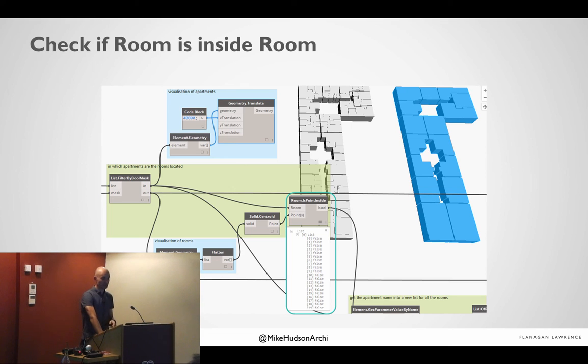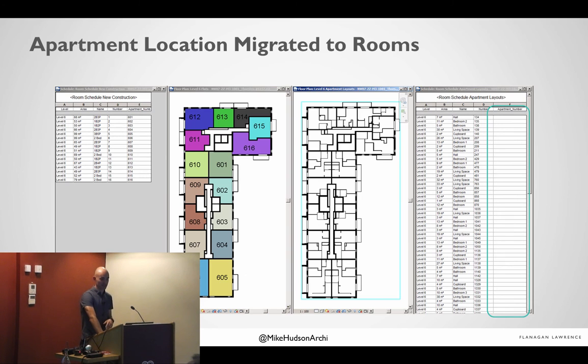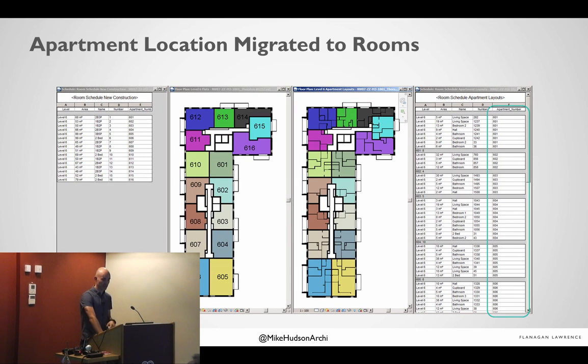One thing I would say though is make sure that you've got your worksets properly filtered before you run this script, otherwise you will corrupt your files. So we learned that. Just be careful. And then the remapping goes through, their apartment data migrated back in. There it is. It knows where it is.